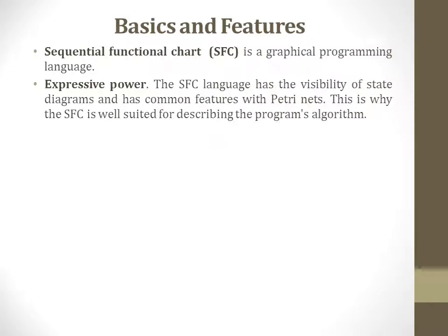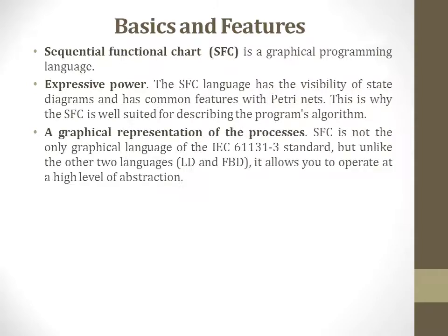Expressive power. The SFC language has the visibility of state diagrams and has common features with Petri nets. This is why the SFC is well suited for describing the program's algorithm, a graphical representation of the process. This is the second feature of this language.